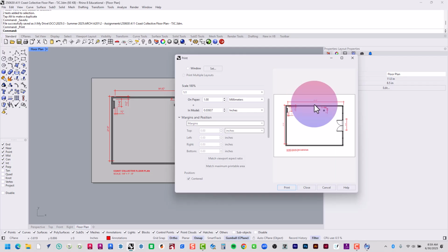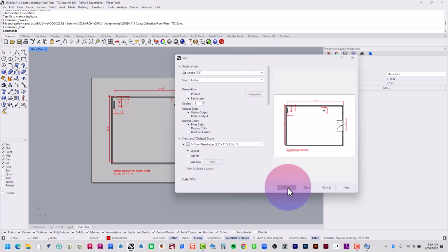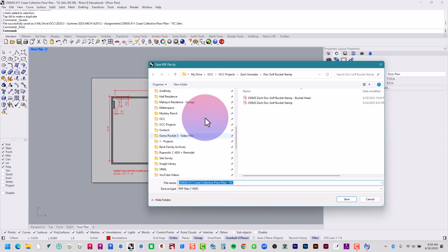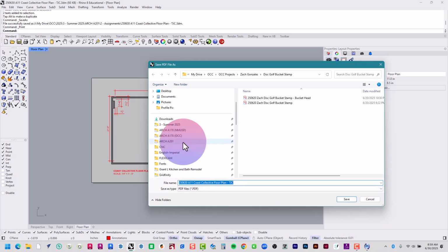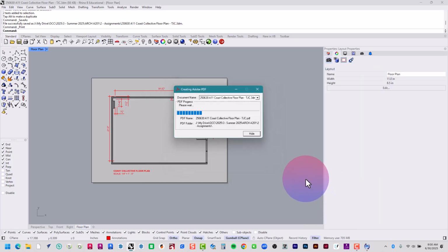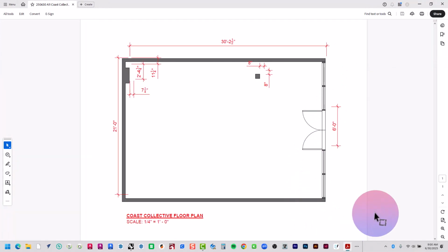If you're using Adobe PDF, usually it'll show you right here. Okay, so now I'm going to print this to a printer. So see if I can print it out to this printer here. Again, 100% scale. You don't want this thing to scale to fit at all. So I'm going to say actual size, 11 by 8.5, and let's hit print.